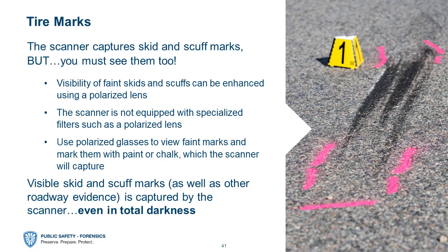Really neat question here. Kind of going back a little bit, but it's very timely. Mike Fisher wants to know, can I combine 360-degree scans with 180-degree scans, if I make my viewing scan range different? Absolutely. There you go, Mike. A warning on that, though. I do want to warn you that you don't want to restrict your scan area so that it's so small that the scanner has difficulty capturing common points. Right. You have to make sure that whatever you do, there are enough common or overlap points to be able to have a good registration.